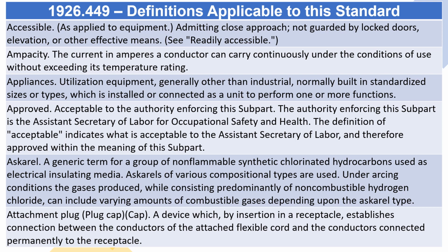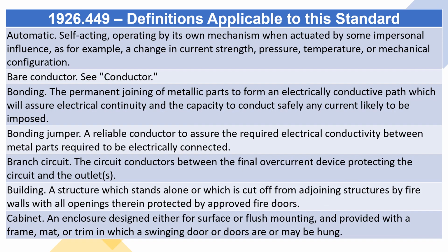Ascarel. A generic term for a group of non-flammable synthetic chlorinated hydrocarbons used as electrical insulating media. Ascarels of various compositional types are used. Under arcing conditions, the gases produced, while consisting predominantly of non-combustible hydrogen chloride, can include varying amounts of combustible gases depending upon the Ascarel type. Attachment plug, plug cap, cap. A device which, by insertion in a receptacle, establishes connection between the conductors of the attached flexible cord and the conductors connected permanently to the receptacle. Automatic. Self-acting, operating by its own mechanism when actuated by some impersonal influence, as for example, a change in current strength, pressure, temperature, or mechanical configuration.